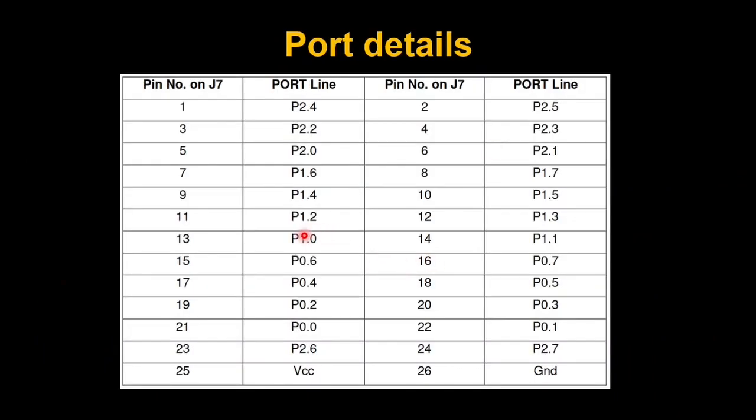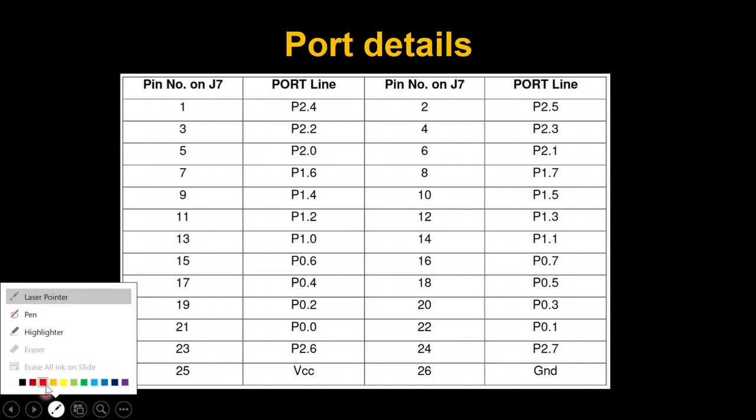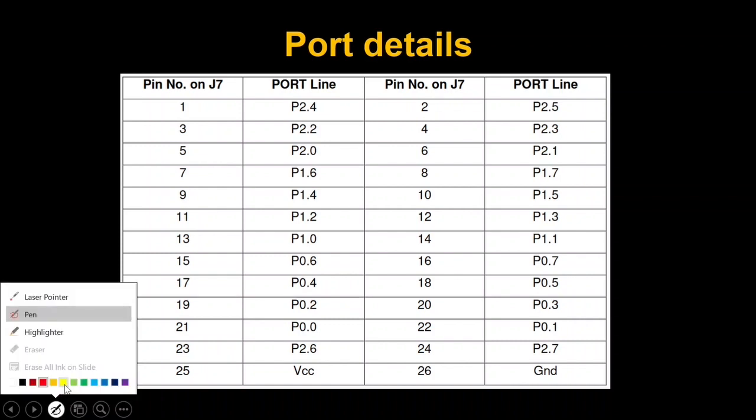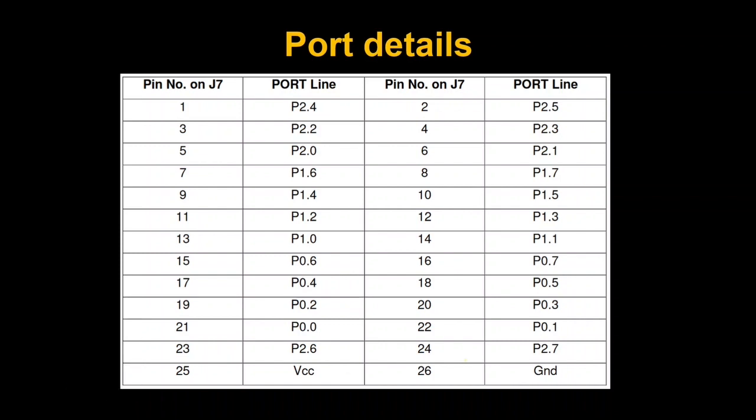So we are going to access your ports, right? If you are going to access your ports, we have to make use of the pins which are readily available. We are having this pin here, right? We are having the 13th pin, which is going to be your P1.0 with which your red LED is connected, and the 14th pin is going to be your port 1.1 to which your blue LED is connected.